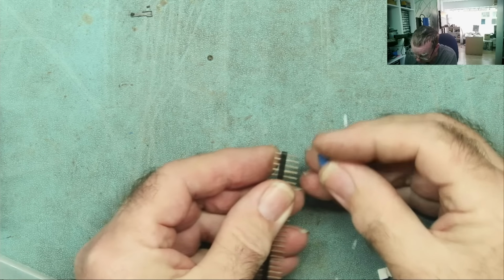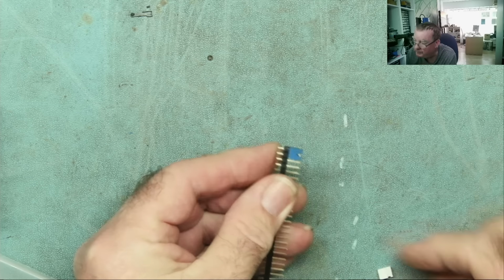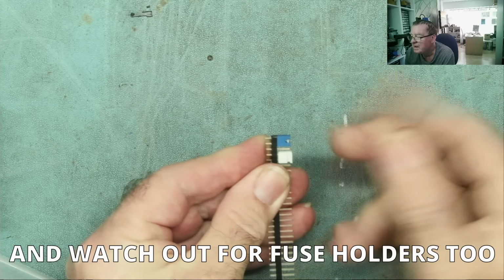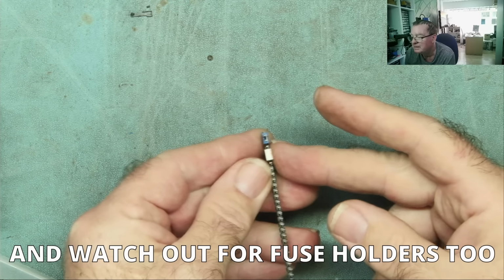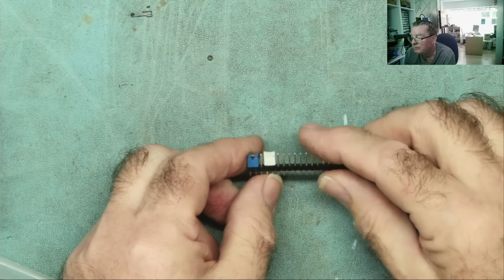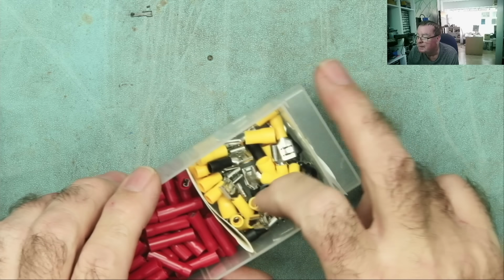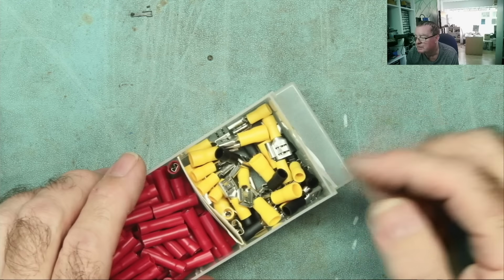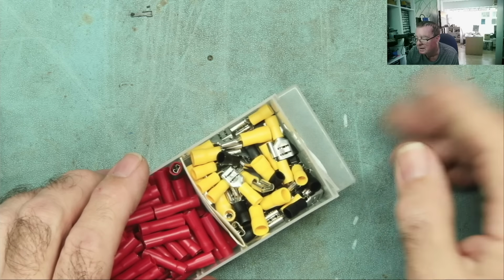A little bit more about connectors, another less than obvious one. Jumpers, you find these on lots of circuit boards. With age, they will tarnish and you'll have a bad connection. So that is another one to look out for. And crimp-on type connectors as well. These usually don't fail in themselves. I mean, you may have a problem with the crimping where the wire comes in.